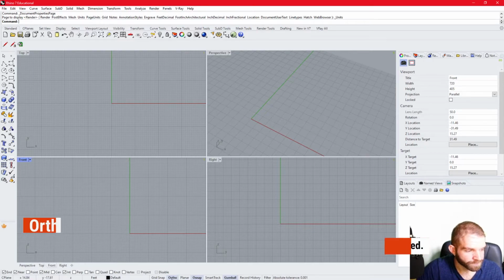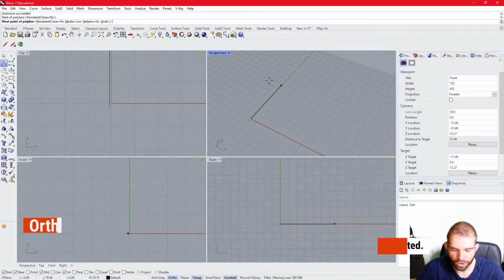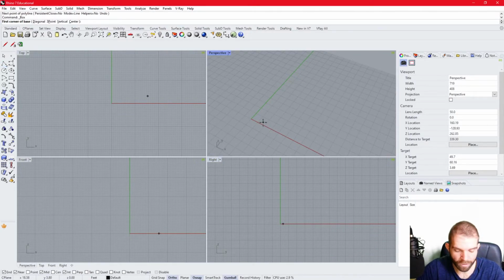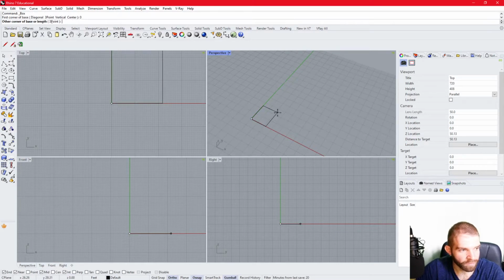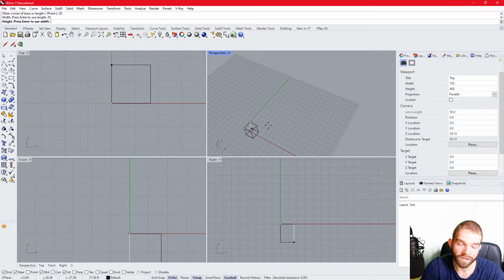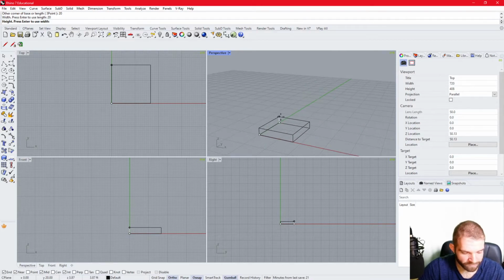But for ortho, if I enable ortho, it's going to lock me into just drawing on those axes. I can't draw any diagonal lines or anything curved. So if I'm drawing a floor, that's going to be fine. I can have ortho on. I'm going to hit on the box command to start drawing a box. I'm typing in 0, enter to start drawing at the center. And then I'll type 20 and 20, enter, and then 20 again, and enter, so that my X and my Y are both 20. And now I'm establishing my height for the box, and I'll just leave it at 1.